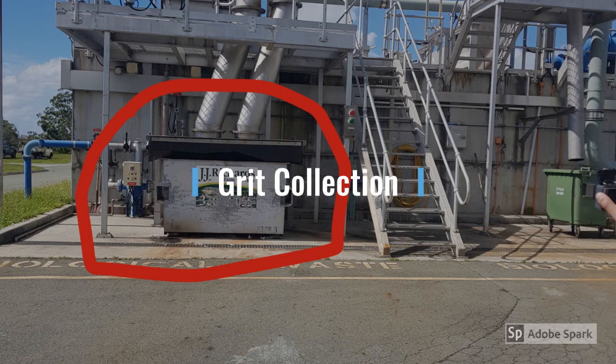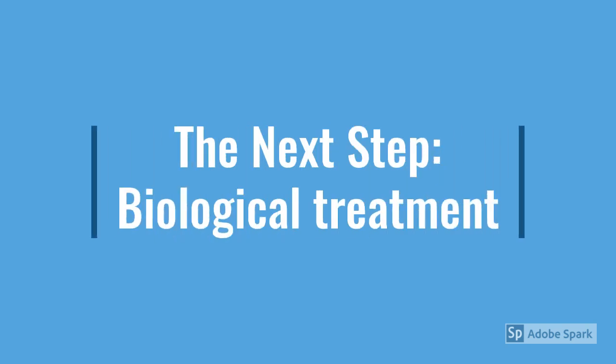Also contained within the inlet works is grit screening and collection. This consists of small particles that have not been digested along with other pieces of small material. Grit screening is an important process as the grit may pass through the process whole and contribute undesirable components to sludge and the dewatering process. These first processes are known as preliminary or primary treatment. The next step in the water treatment process is biological treatment.